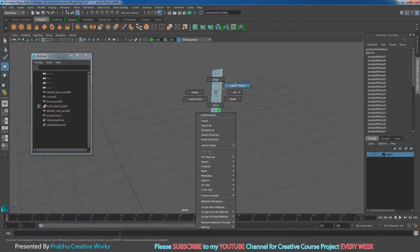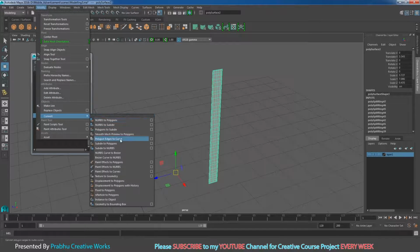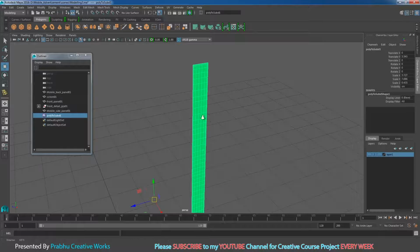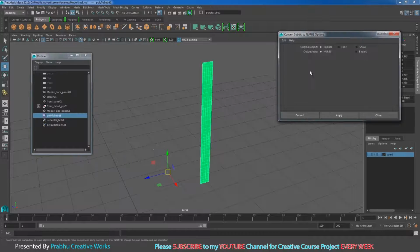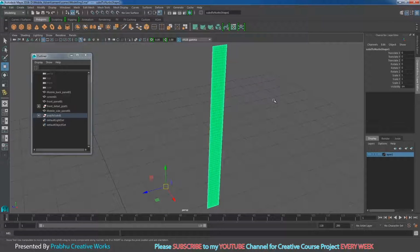Now right click and choose object mode. I select my object, go to modify, convert. Now you want to choose the poly to sub-D option box. Here you need to give full value, so keep the slider all the way to the end, and choose create. Now see here, it will be converted to a subdivision. Now select the poly to sub-D, go to modify, convert. Now you want to convert subdivision to NURBS. In the option box, choose replace, choose NURBS and choose convert. So now our object will be converted to NURBS.